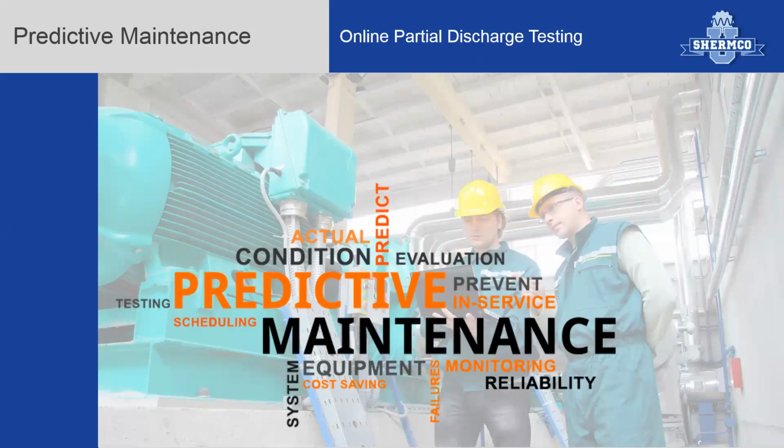All right, since partial discharge is a form of predictive maintenance, let's talk a little bit about what is predictive maintenance. Now, predictive maintenance techniques are designed to help determine the condition of in-service equipment in order to predict when maintenance should be performed. Now, this approach promises cost savings over routine or time-based preventative maintenance because tasks are performed when warranted. Now, the main promise of predictive maintenance is to allow convenient scheduling of corrective maintenance and to prevent unexpected equipment failures. The key is getting the right information in the right time period.